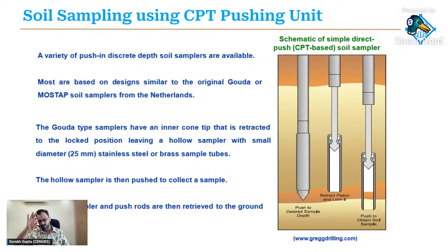You can do a CPT push, and understand where the silt is, where the clay is, where the loose pockets are, and so forth. Then you can shift the apparatus maybe a couple of feet aside and push again, and you can actually choose the particular depths at which you want to take your undisturbed samples. I want to mention this because this is great.